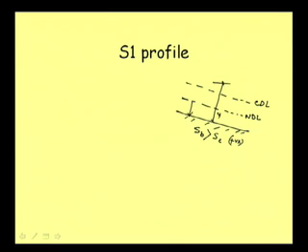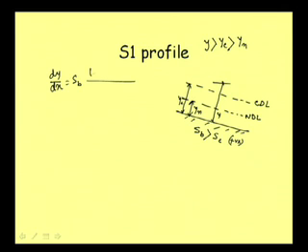This depth is YN, and this is critical depth YC. And the condition that we are getting is that Y is greater than YC, and YC is greater than YN here. And then if we go back to our equation again, dy/dx is equal to SB times (1 minus (yn/y) cube) over (1 minus (yc/y) cube). Well, the same equation.